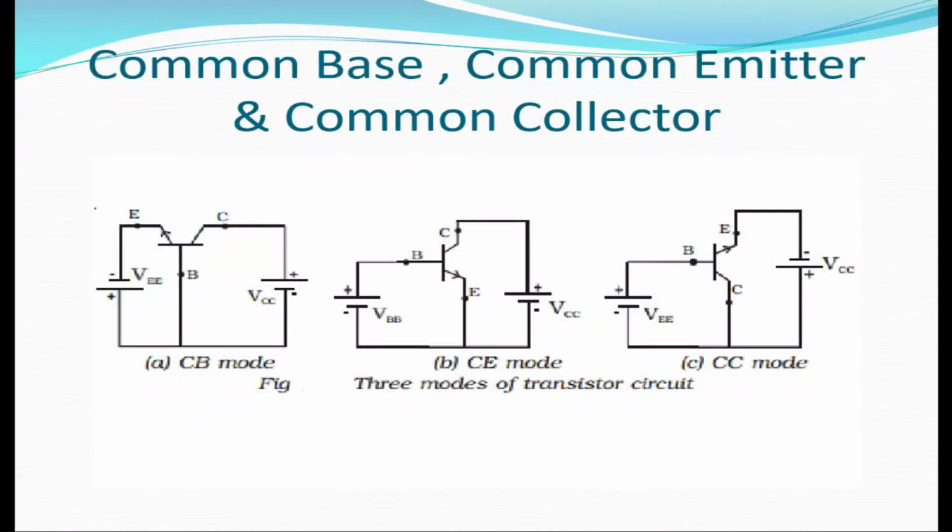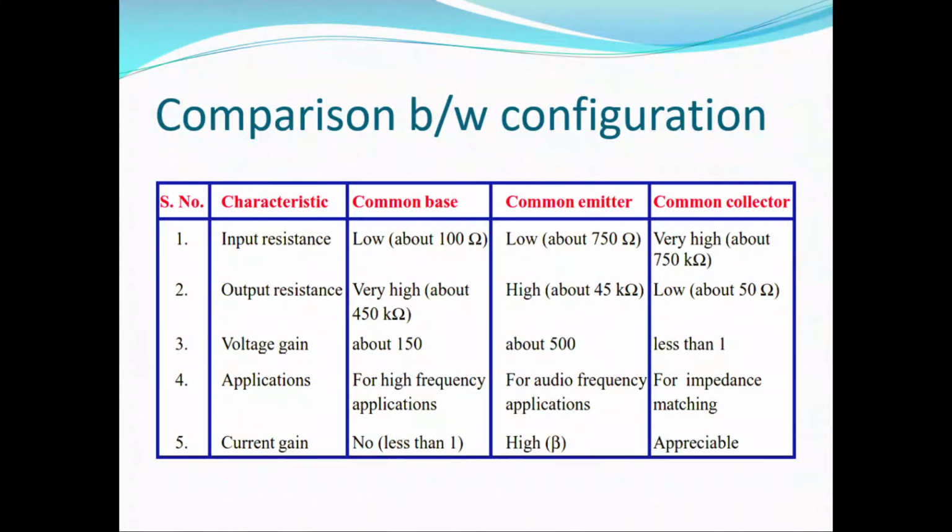We have seen that transistor can be connected in any one of the three configurations. It behaves differently in different configurations. In which configuration should we connect a transistor? This depends upon the particular application we desire. The parameters that govern the suitability of the configuration are dynamic input resistance, dynamic output resistance, DC current gain, AC voltage gain, and leakage current of the transistor in a given configuration.